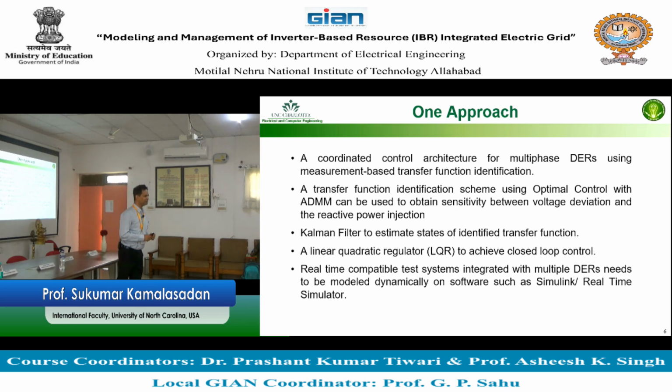Control comes in different levels. One level is device level control, where the device controller works on the device to take care of the objective of the device. For example, for the inverter, one device level control is to maintain the voltage of the PCC. PCC is the point of common connection, or point of common coupling. The inverter will look at the point where it is connected. It will maintain the voltage at that point clean, depending upon whatever power is pushed from it.